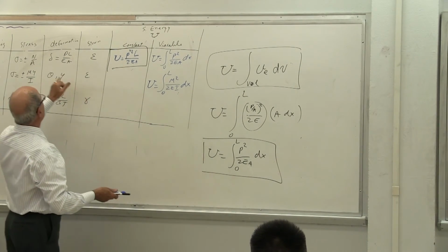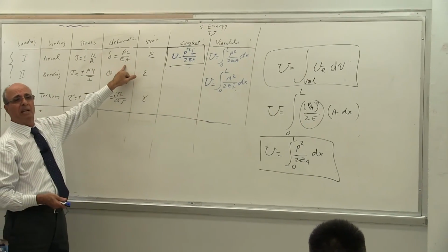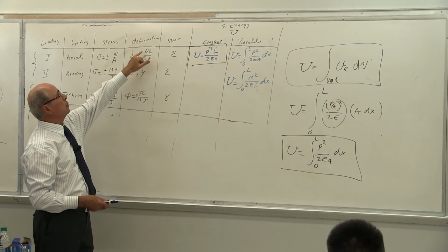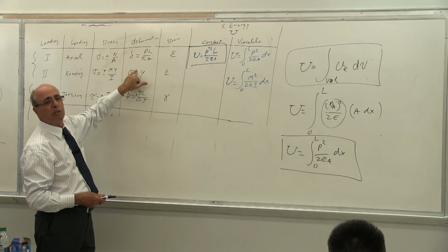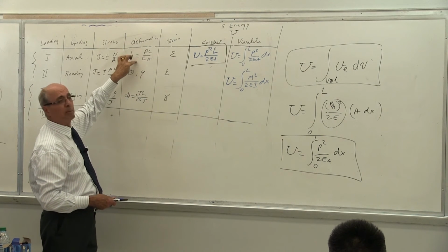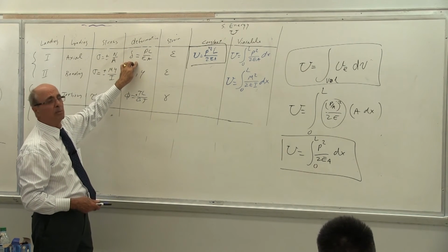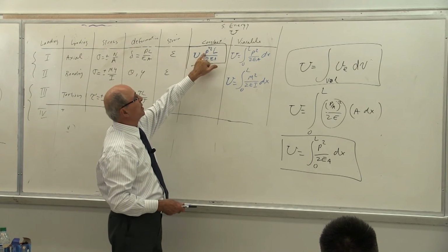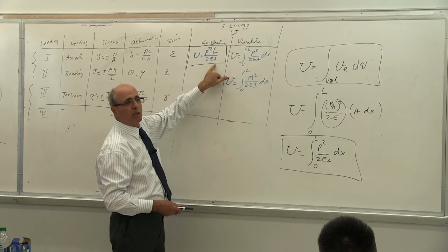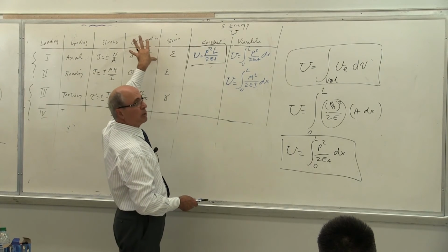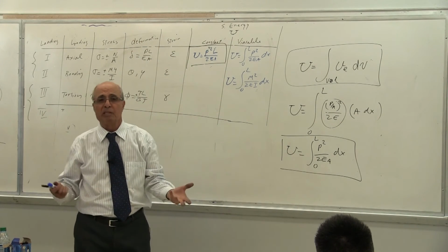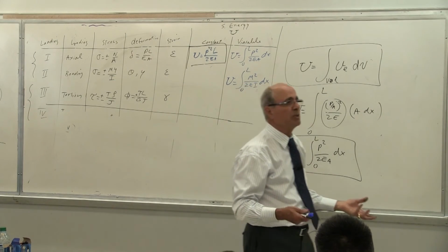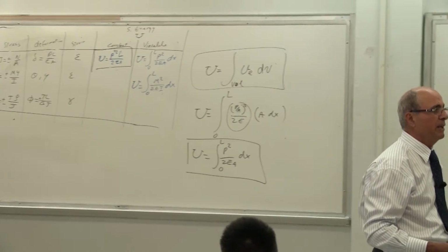Look at the key. Everybody remembers PL over EA? Yes or no? So all you have to do is make the load squared and then put a 2 here. In other words, add a 2 there and put a 2 here. Everybody see what I'm talking about? Look how routine that is: P squared L divided by 2EA. Of course, EA belongs to the axial load. EI belongs to the beam. Anytime we were calculating theta and y, we were using EI. Yes or no? Correct? Okay.